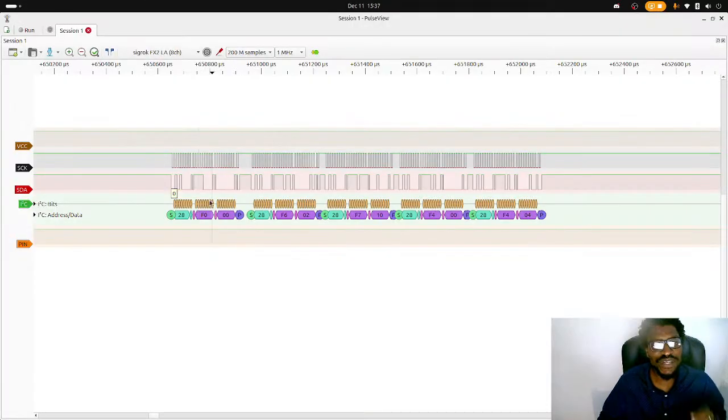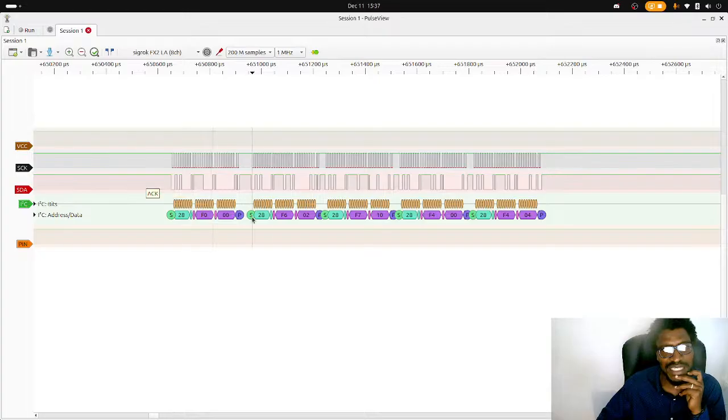So we're definitely talking to the right place, and I see the initial barrage of messages. Perhaps the first thing to do is to look at all of these messages and decide what they actually mean. There's an F0, a 2A, an F6, an F7, and then two F4s. These two look to be toggling the actual device.